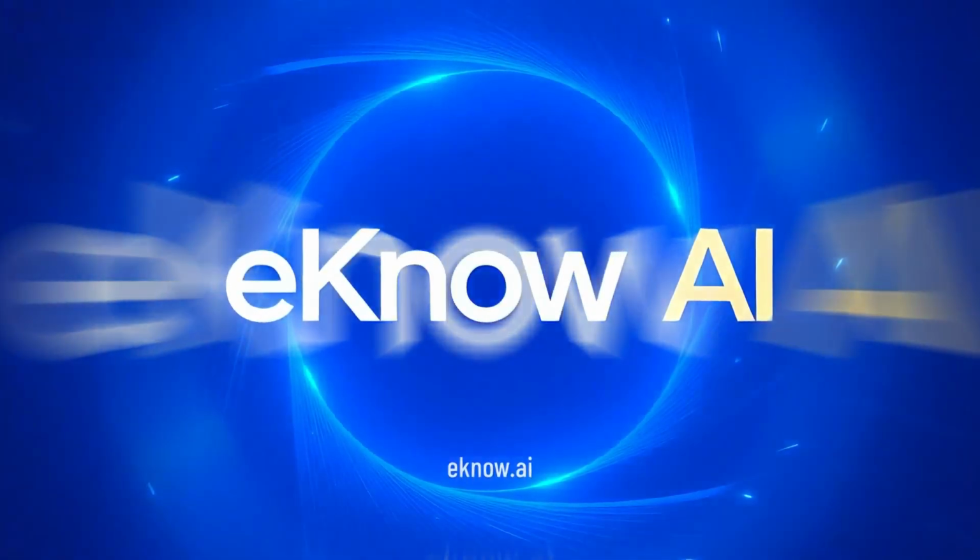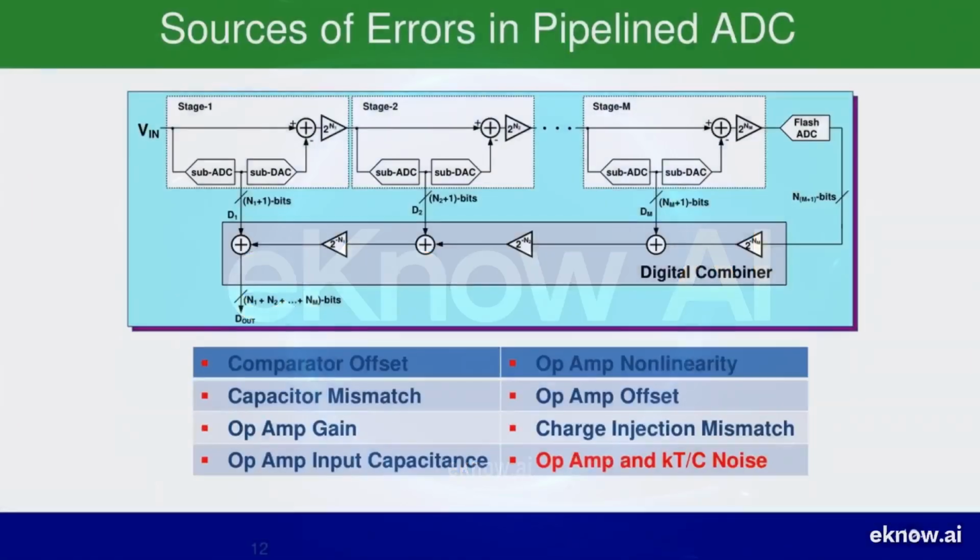We've seen this ideal block diagram of a pipelined ADC before, showing how each stage processes the signal and passes a residue to the next. Now, we're going to look at this from a more practical, real-world perspective. The components we use to build these stages, the op-amps, the capacitors, the switches, and the comparators, are not perfect. Each one has non-idealities that can introduce errors into our conversion process. This page gives us a roadmap of these key sources of errors.